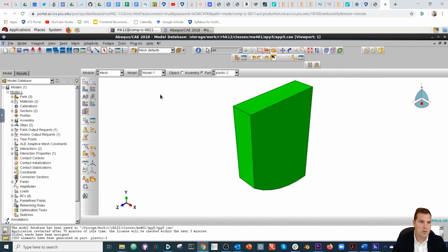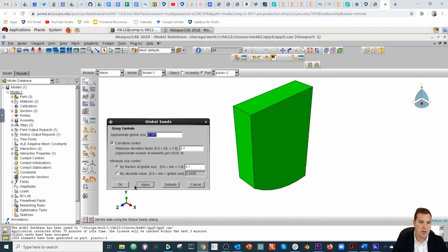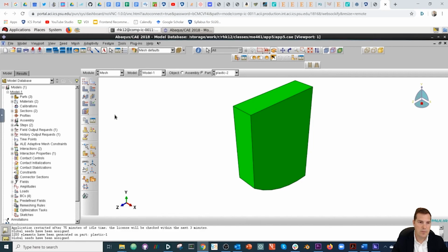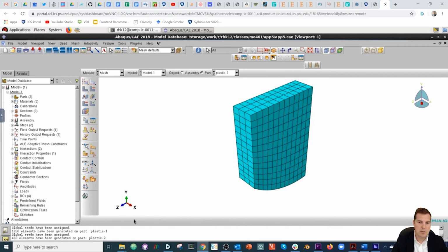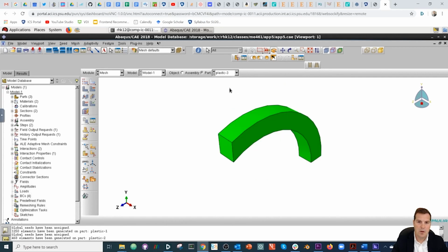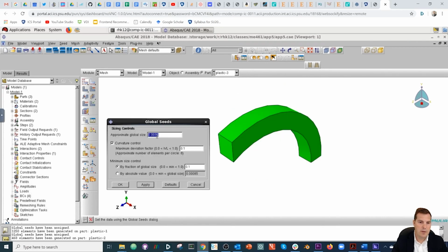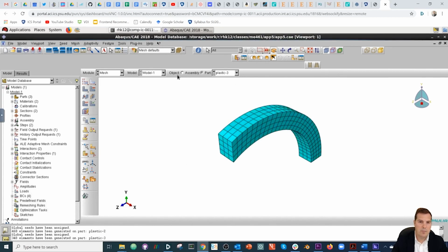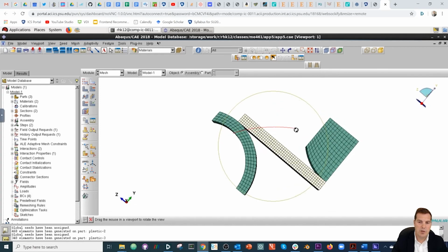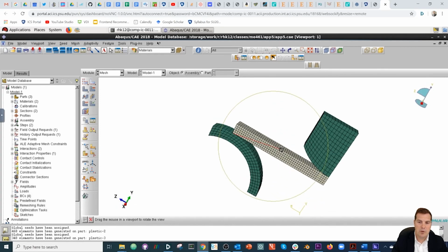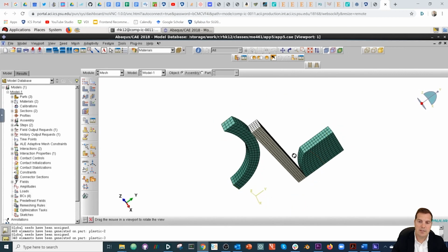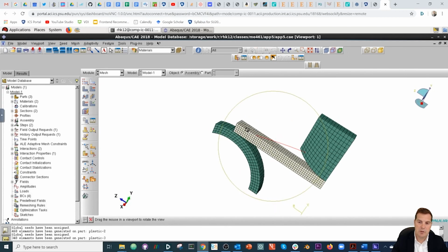Go on to the indenter, and we'll go with 0.003. Say yes. And finally, we'll go here to also 0.003. Okay, so if we look at there's our mesh, looks pretty good. Pretty surprised we were able to get hexahedral meshes out of this curved geometry, so that's pretty good.